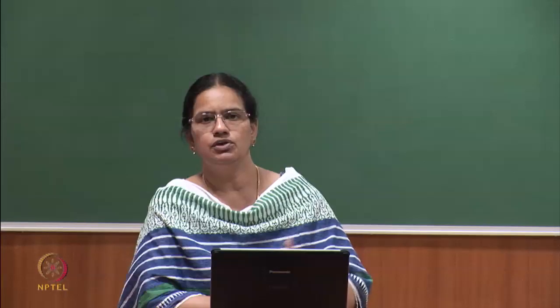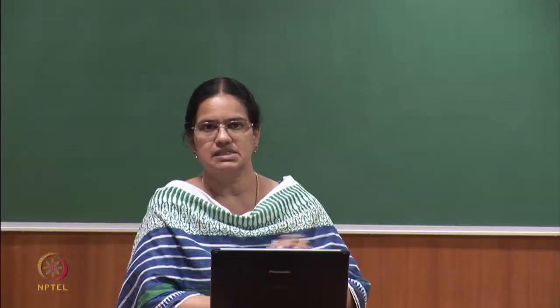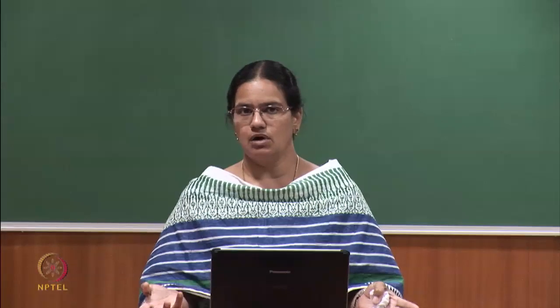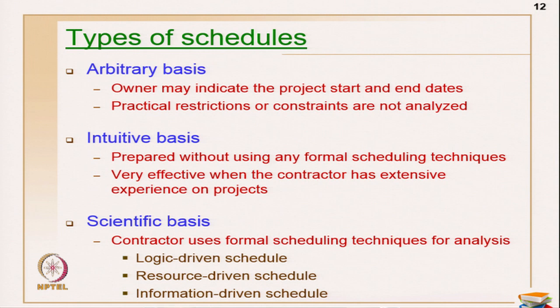So, what is a logic driven schedule? As the name implies, the logic of the construction drives the schedule. For example, after the foundation, only then can you do your columns or beams and slabs. That logic primarily drives your schedule, and that is called logic driven. The next is resource driven. Suppose I have two or more crews for doing a particular work. Based on the resource crews, I can do the work in parallel, or based on the smaller number of scarce resources that I have, I may have to execute the project sequentially.